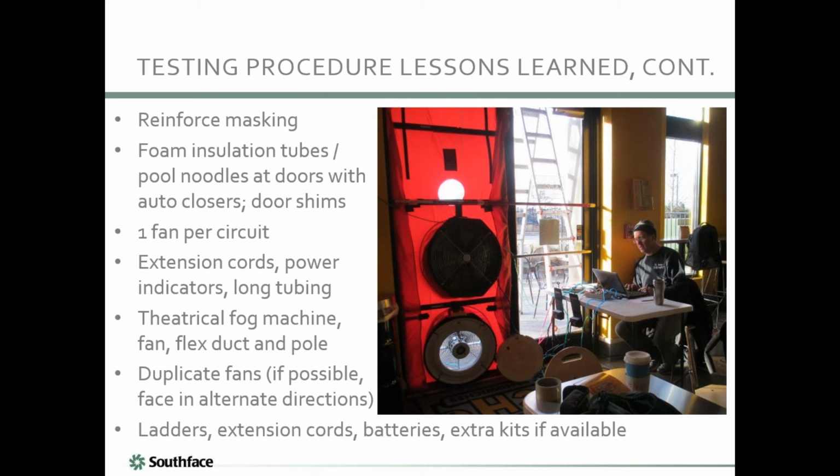I would definitely say, and you probably agree, that I have more confidence in our depressurization numbers, because if we're masking from the outside, it tends to suck the mask in. We visually saw some cases where, in the pressurization test, the masking was failing, and you could tell. So it was definitely more of a challenge to get good data. Sometimes it was great and not a problem, and the stuff was easy to tape over. Sometimes it was much more challenging.